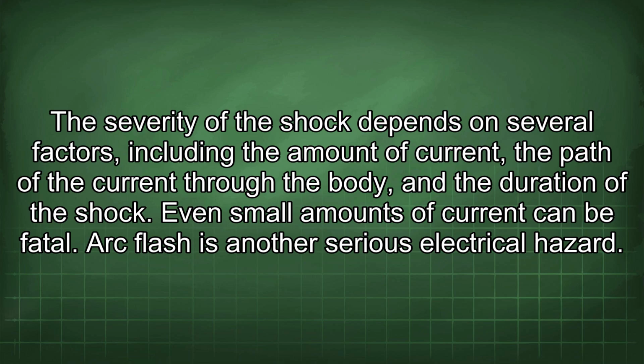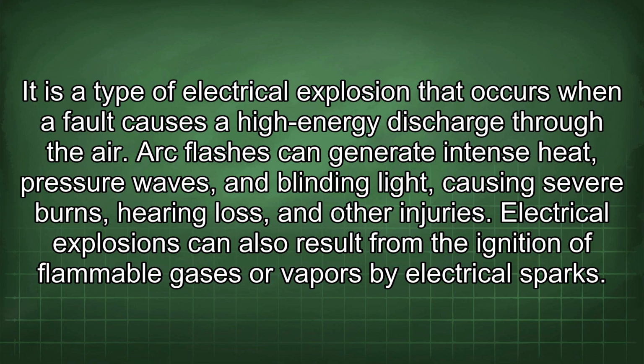Arc flash is another serious electrical hazard. It is a type of electrical explosion that occurs when a fault causes a high-energy discharge through the air. Arc flashes can generate intense heat, pressure waves, and blinding light, causing severe burns, hearing loss, and other injuries. Electrical explosions can also result from the ignition of flammable gases or vapors by electrical sparks.